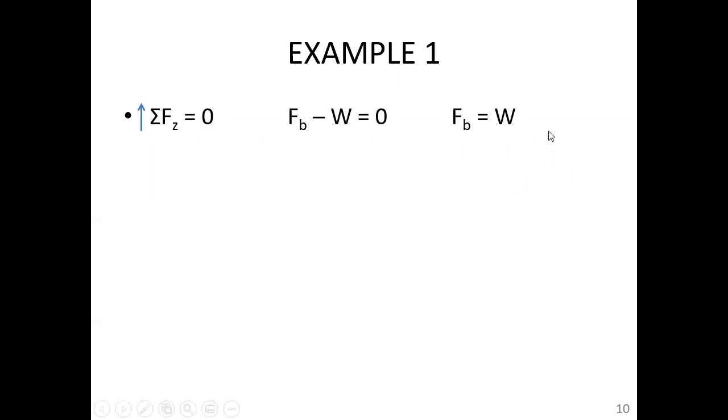And so when we resolve that vertical static equilibrium equation for this free body, the buoyant force is equal to the weight, Archimedes' principle. The weight, again, is equal to the specific weight of the cube. In this case, gamma c is the specific weight of the cube, and Vc is the volume of the cube.